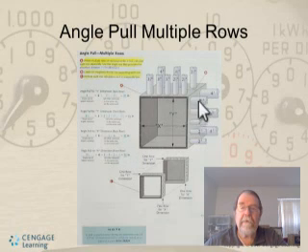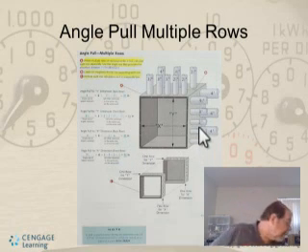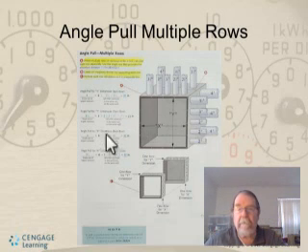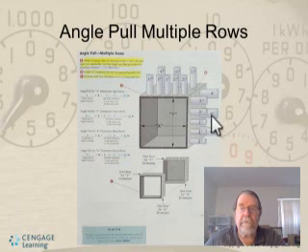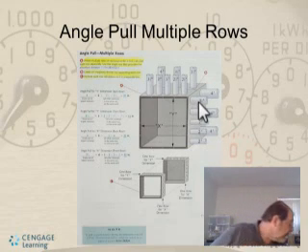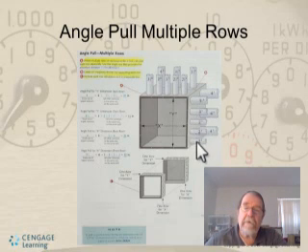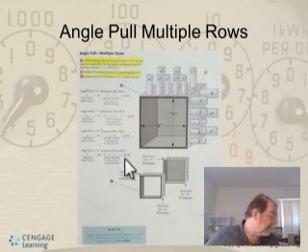And then here you're doing the same thing. You're taking, multiplying by 6, your 3.5, and then well, this one here is doing the back row. They do the back row first. I always do the front row first, but they're doing the back row here, 4-inch, and then add those together. 6 times 4 is 24, and then these two give you the volume. And then this one here, you take, I think it's a 3.5 inch times 6, and then you add these other 4 conduits to get you the volume.